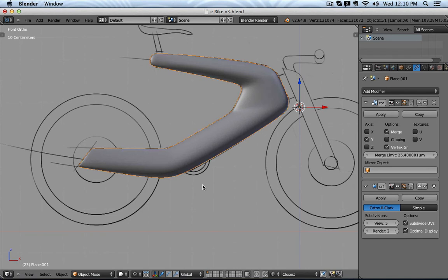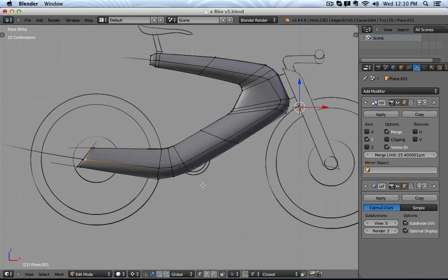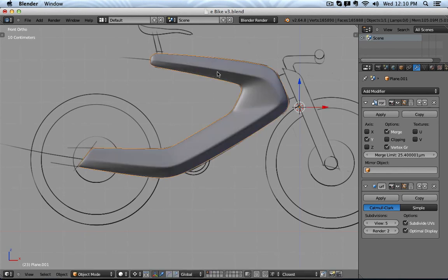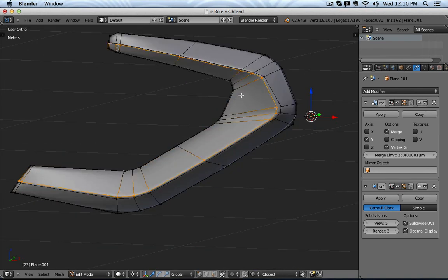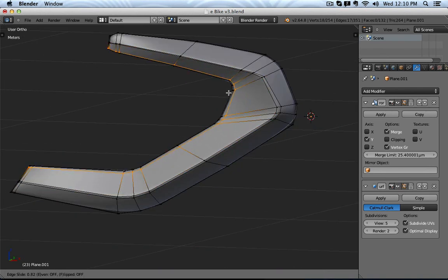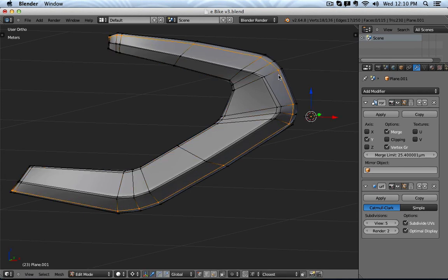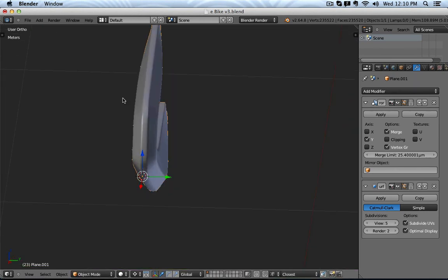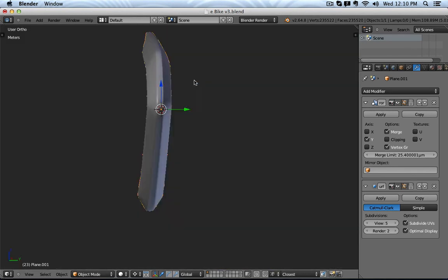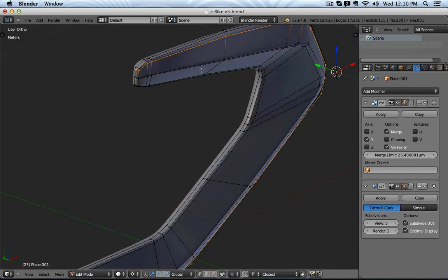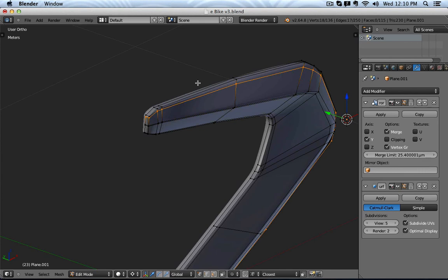So instead of using a cube and then extruding it out, I use just a flat surface, put in a crease line. And for example, right now I'm going to recrease that surface even tighter, so it's really clearly a visible separation line. And then if maybe you want the inner and outer edges to be sharper, you can do this like this. And let's say the outer edge should be more round instead of being so straight.